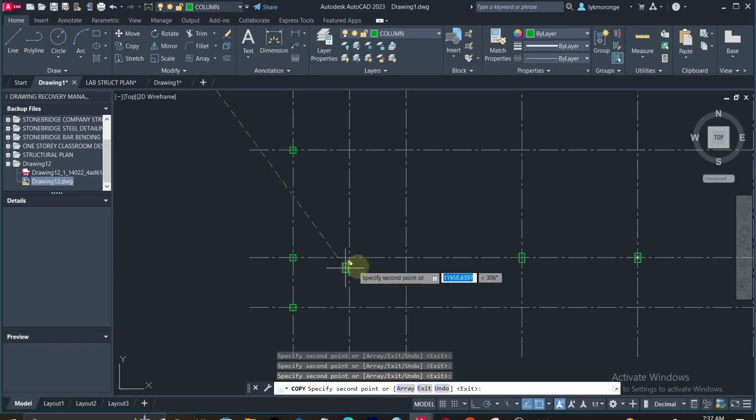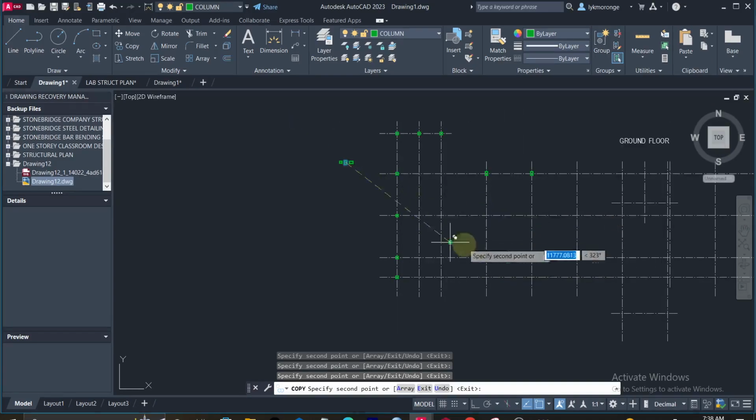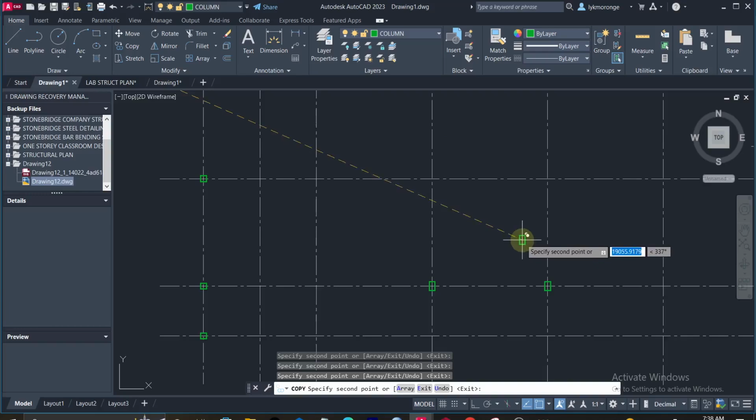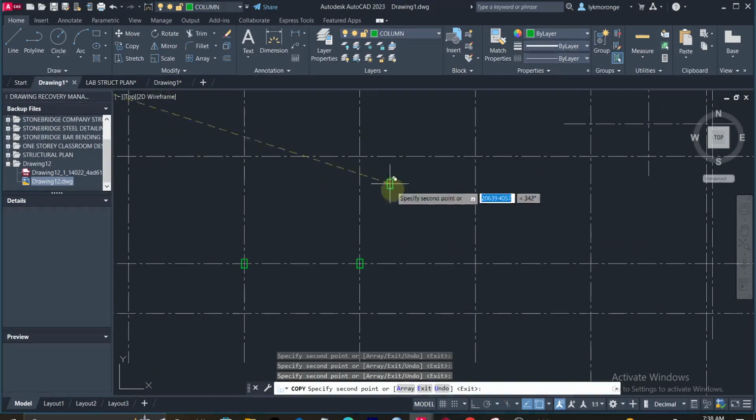So I didn't even use columns of the same size. I want just to assume this is the best sizing members, and then once I design and then they fail, I can come see the mitigations that I'll do. And also remember this is just a one-story building. It doesn't carry a lot of weight, but we'll have a lot of issue on the slab because of the span.